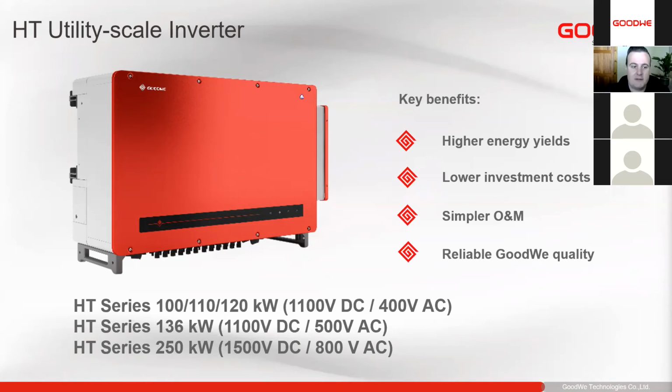So you'll see we have multiple different models, 100, 110, 120, at 1100 volt DC and normal 400 volt AC. So these are all your normal rooftop inverters, but can also be used for ground mounting. The 100 kilowatt has 10 MPPTs, the 110 and 120, and all the rest all have 12 MPPTs. We have a 136, you'll see that's 500 volt AC, that's going to be mining applications and things like that. And then the 250, which is more utility scale for big utility plants. These devices give us high energy yields, lower investment costs, simple O&M, and reliable quality.